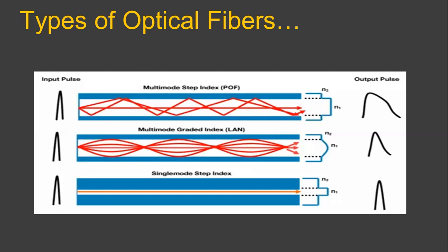And this is called the graded index cable because you can see here the refractive index profile of this fiber is not taking the shape of a step. Instead of that, it is gradually changing when one moves from core to cladding. From the axis of this cable, when you are moving away radially, you can see the refractive index is gradually decreasing inside the core.